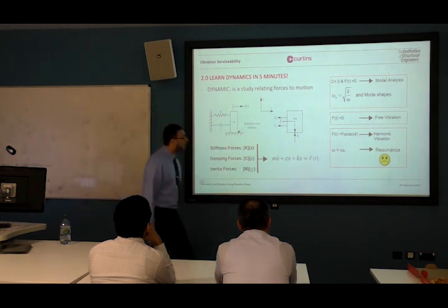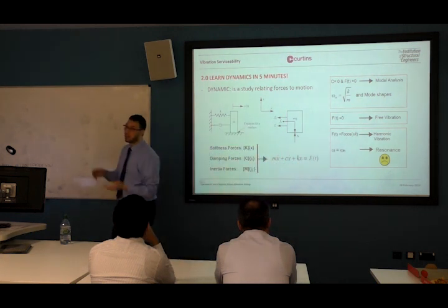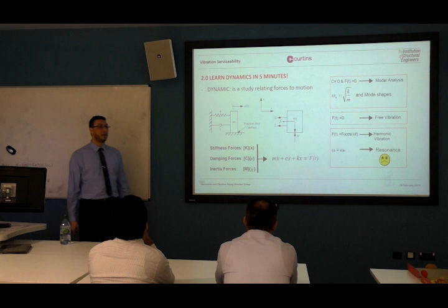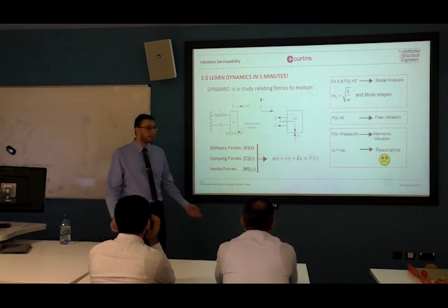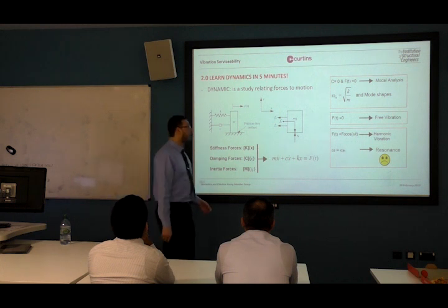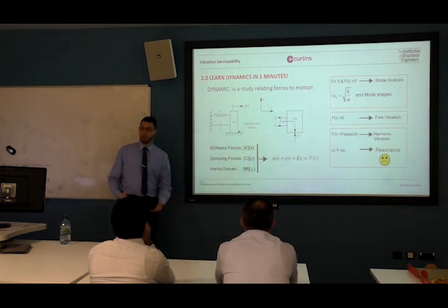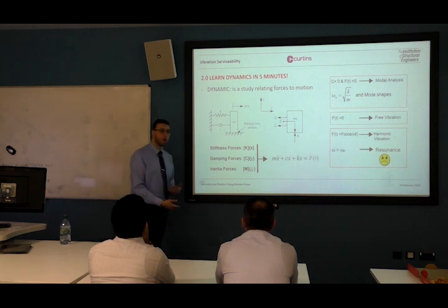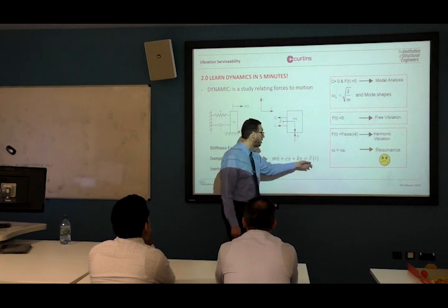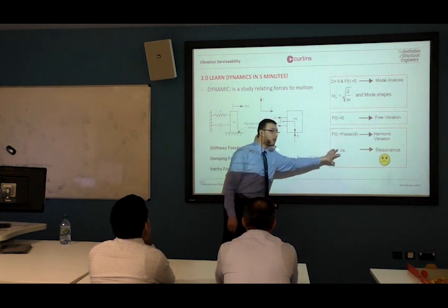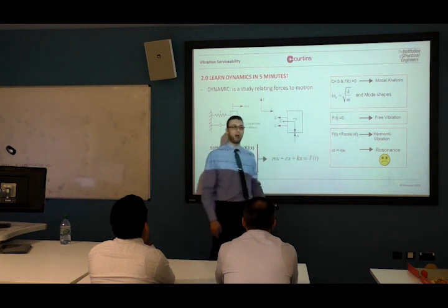You might have F as a harmonic load. F can be any shape, any type. It can be an arbitrary load like an earthquake. It can be an impulsive load like a blast. It can be harmonic, sinusoidal. It can be periodic; periodic is a sum of sinusoidal loads. And if it's harmonic and has the same frequency as the oscillating body, then we have a problem.